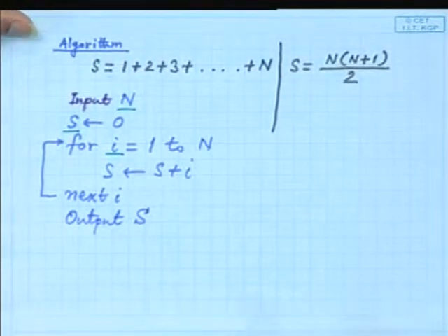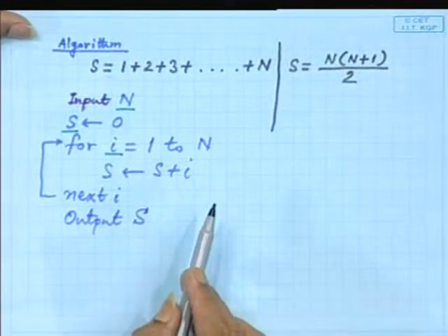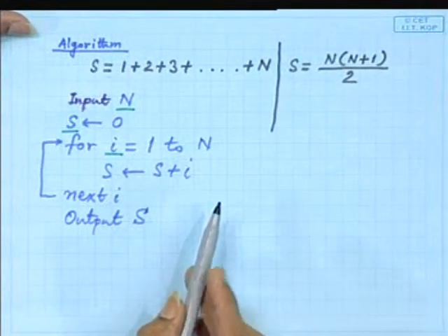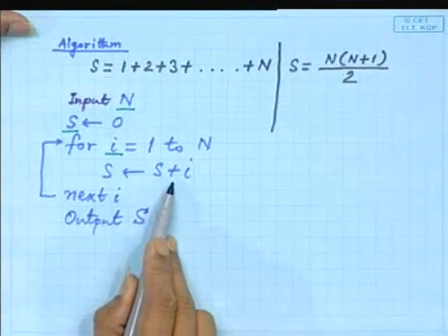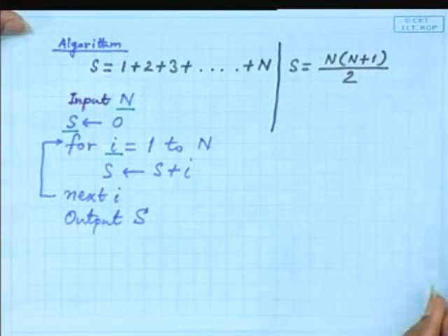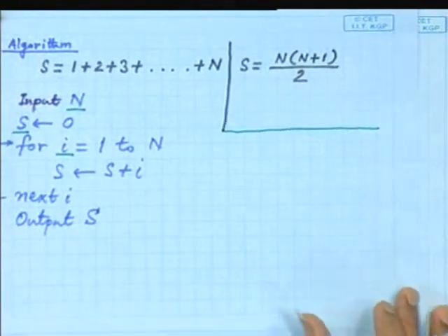So we will put 3 registers in our circuit, and at the same time we have to find out what combinational blocks are required for any arithmetic or logical operation. Here we find it is the addition operation, right? So if we try to map this into hardware, how will it look?